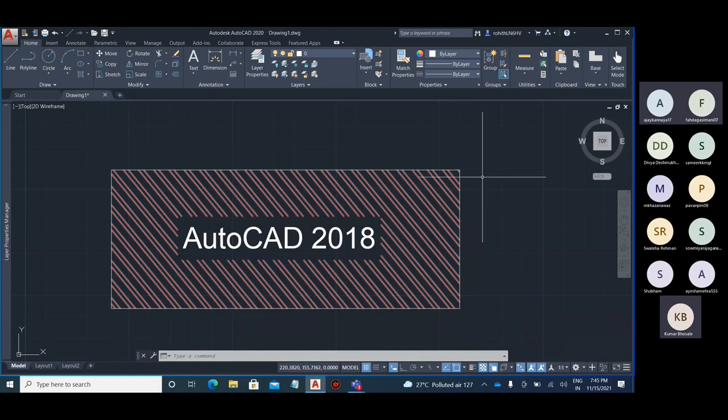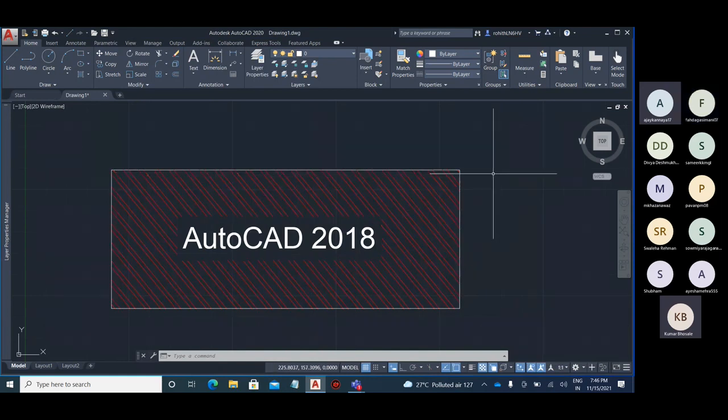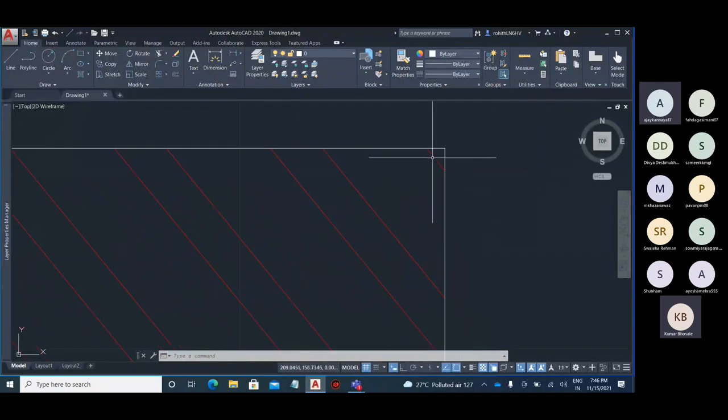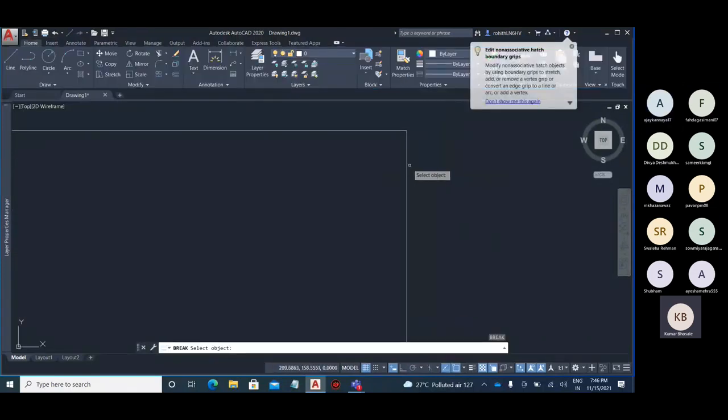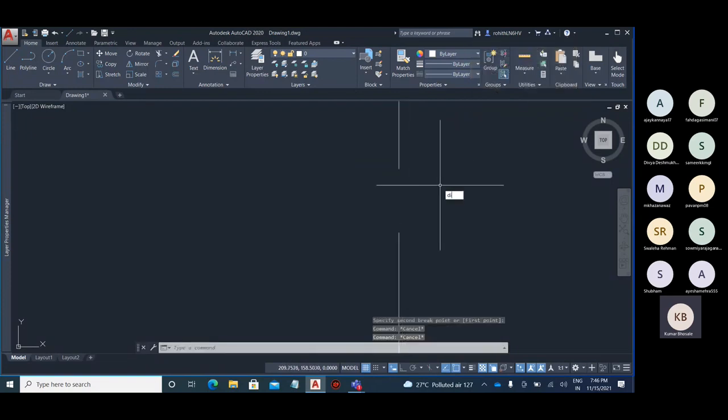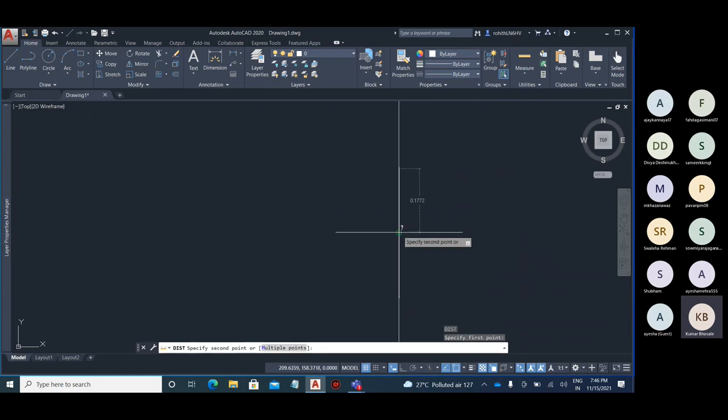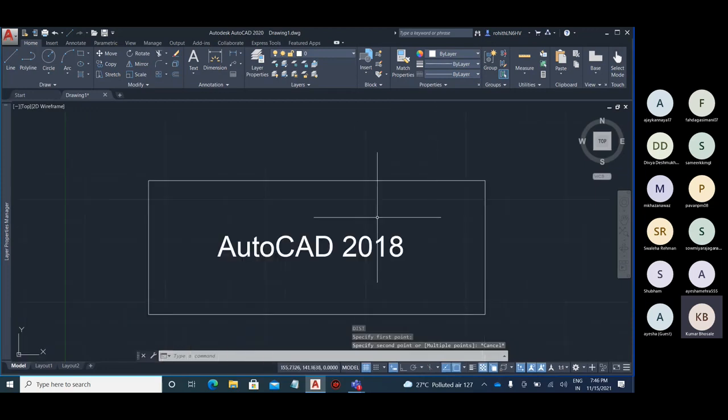Sir, also can you say about gap tolerance? Yeah, gap tolerance. Okay, I'll tell you. So over here, let's say you have a break in the line, and let's see how much is the distance from this point to this point. Can you see it is 0.1? So if I give zero tolerance, what zero tolerance means is that I cannot tolerate anything beyond zero.